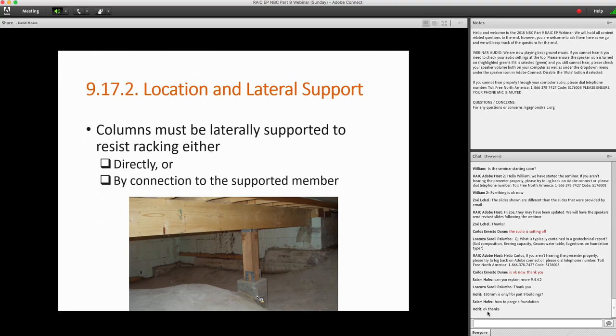Now, technically that's a pin, if you ask any engineer. This is quite a squat column, and there are other elements that are restraining it as well. So typically we want the column base to be as close as possible to the base of the footing and the pier.